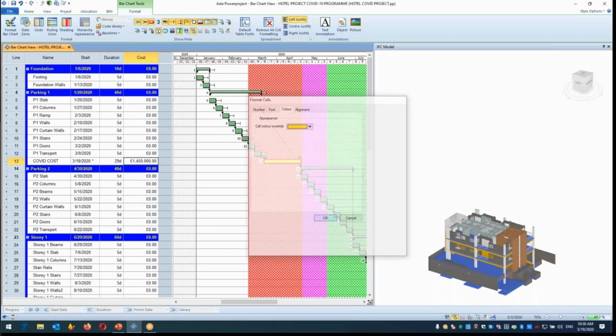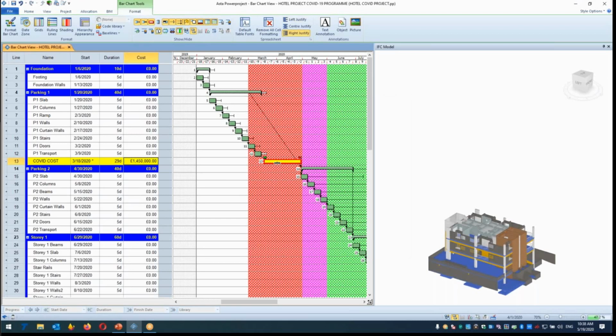Okay, and if in this activity we have extended it a little bit longer, you can create the activity for longer, so I have extended this activity, not 29 days, but more, 48 days. You can see that the total cost is automatically increased for the remaining time.